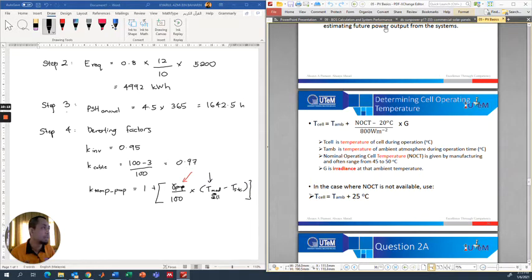Okay, but when we replace in this equation later, T_STC, as we recall, is always 25 as well. So basically, we are going to put in the value of 34 degrees in this part here. Because T module is ambient temperature 34 plus 25, and then we minus 25 again.